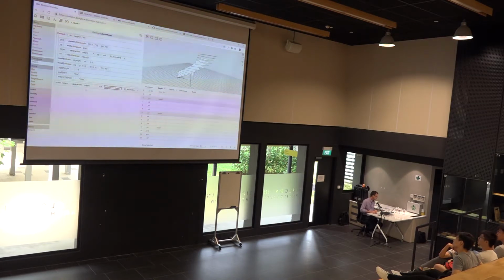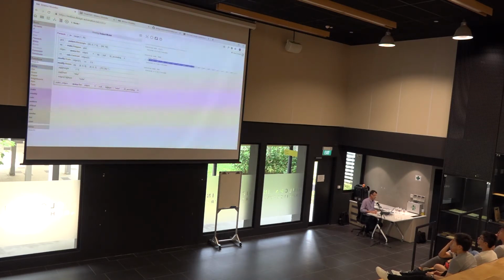So this is basically saying, get me all the edges in the whole model, null means the whole model, where the type is equal to outer, because I created this outer type. That will get me a bunch of edges. So let's just print that, check that I've got some edges. Yes, I've got a bunch of edges.